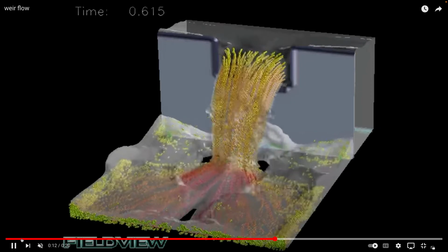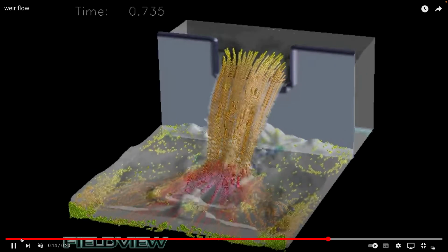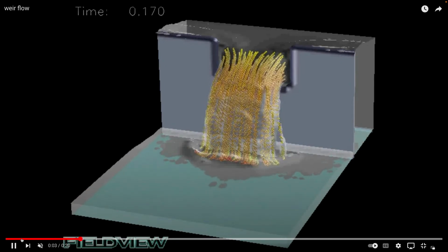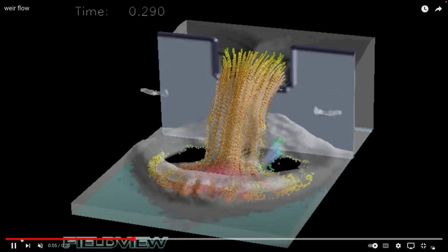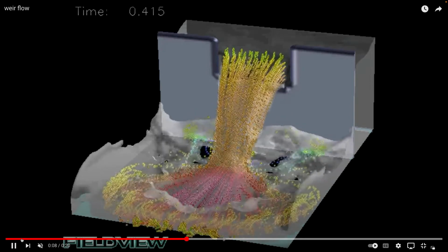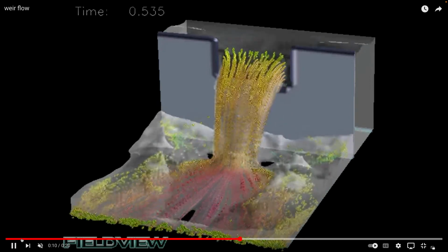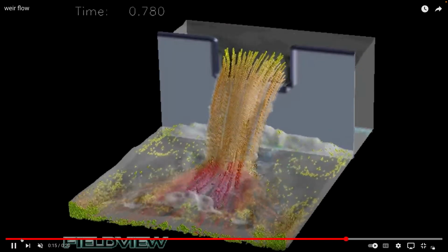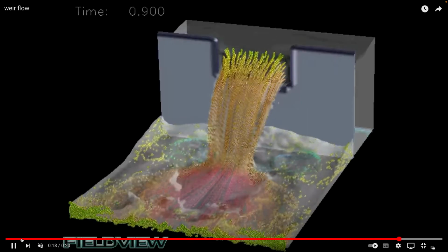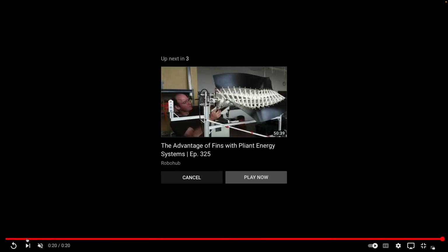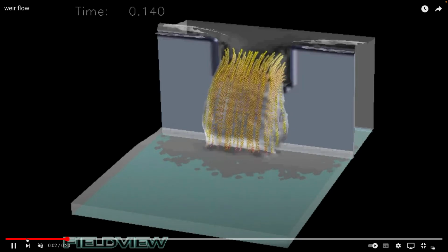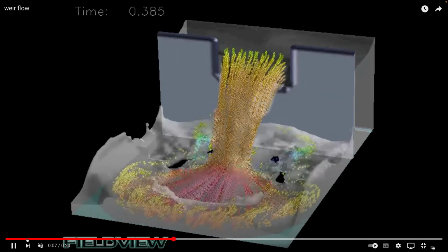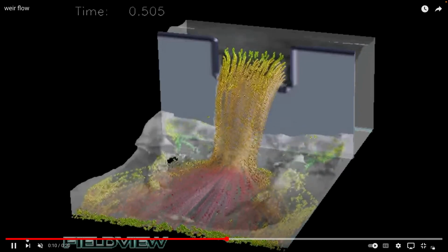And so we can do it in an open channel. If you're an environmental engineer, you might be sent into the woods to gauge the flow of this ephemeral stream that's running. And so what you do, you take a board with a notch cut in it, this size, and you stick it across the stream, allow it to build up behind, and then measure the depth to which it comes across the orifice as a proxy for the flow rate. And so we'll see how we can use overshoot or undershoot weirs to be able to do that.